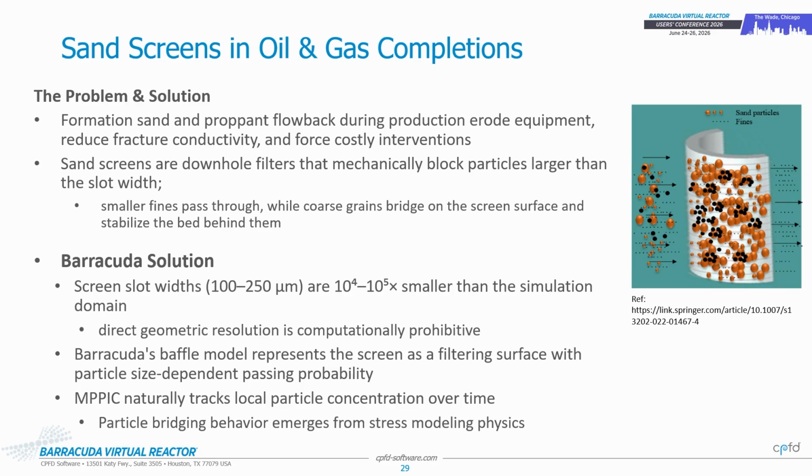And that's where we have a nice feature here. Again, the interesting thing about this feature is our users have used baffles over the years, typically thermal baffles and so on. But we have found another interesting use for this feature, which is to use a baffle as a filtering device, right? So essentially what we're saying is this entire screen is going to be modeled as a baffle, such that the baffle can filter out particles. And how can it filter out particles? Well, it turns out we added in a feature for this.